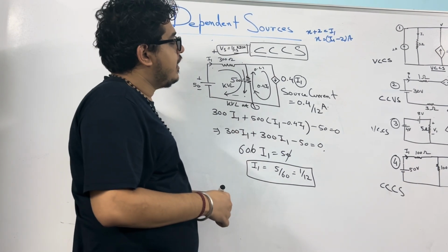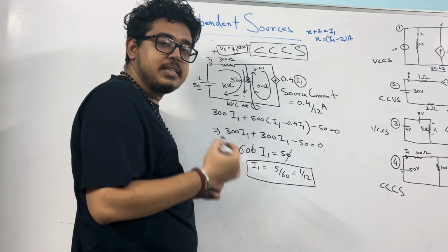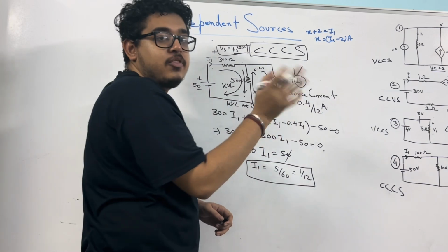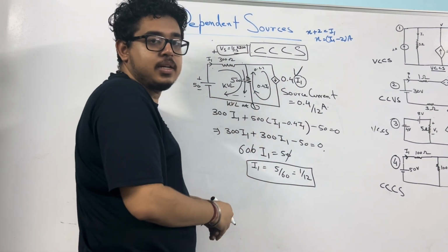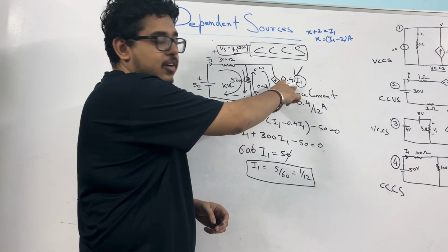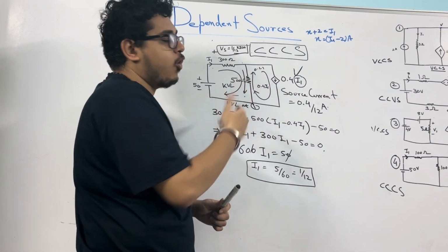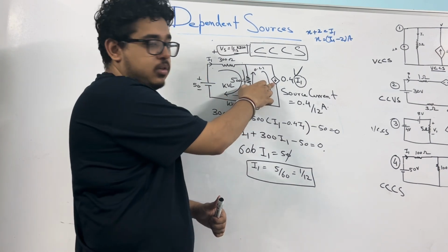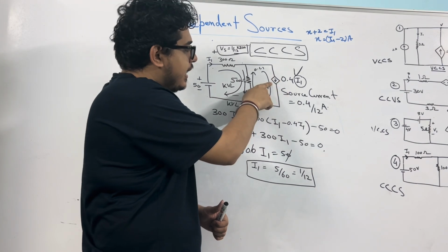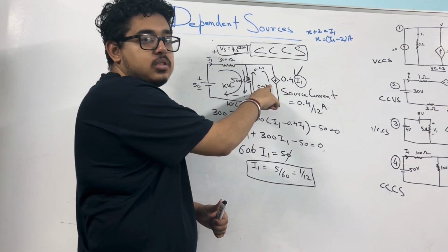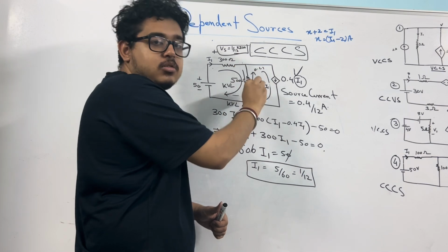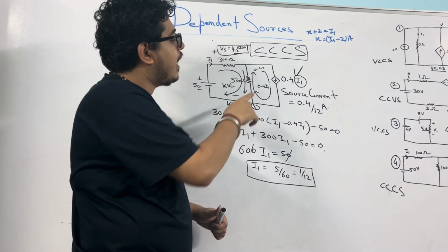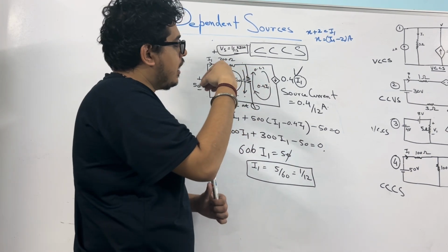So what we learned is that first we have to use the basic techniques, KVL and KCL only. First we have to find the value on which the source is dependent. Finding this value will easily let us solve all the problems. This is nothing tough, this is very easy. We just have to look, and not think that this is only a current source. If it was a voltage controlled current source, I still have to treat it as a current source. The value just depends on the voltage at some point of the circuit. So I have to check the source and work accordingly.